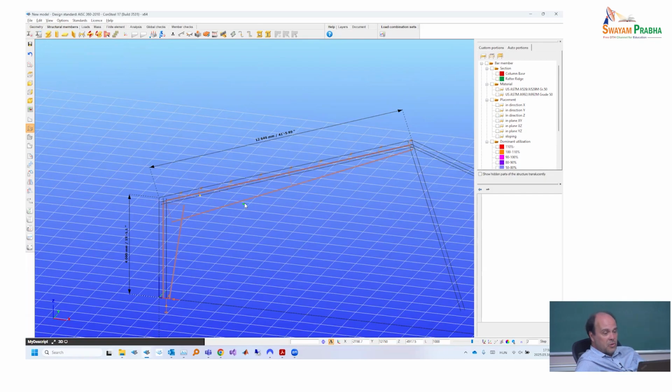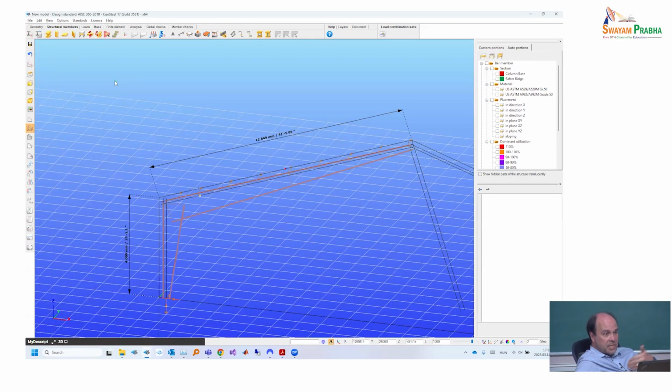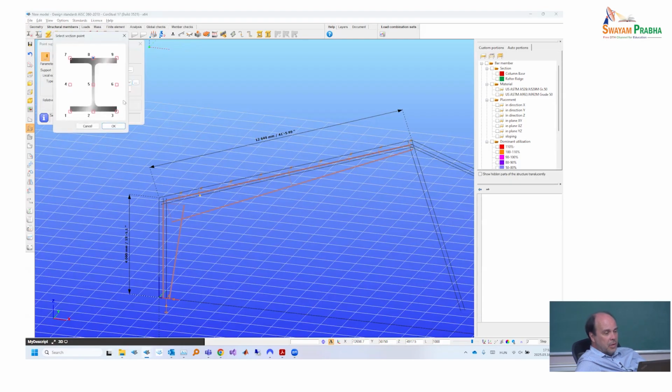Now let's do also with the flange braces. As it is visible on the picture, we have a flange brace on the 2nd, on the 5th, and then on the 7th, 8th, and the 9th purlin. That goes very easily. That's, and again, a support. As we said, this will be another lateral support, but this time attached to the bottom flange. So point support Y is fine. Instead of top middle, we will select the bottom position. We cancel the 100 millimeter because this we don't need.